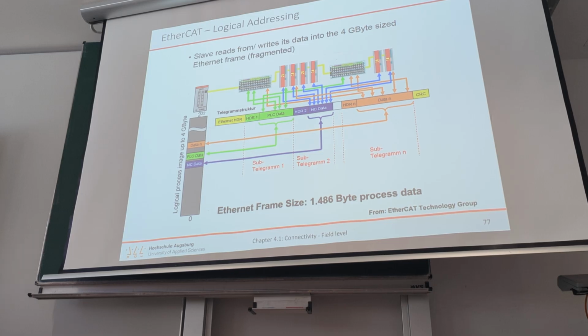If you calculate that, then you see that roughly a frame takes about 120 microseconds, and that's why it was difficult to get control loops that were faster than 120 microseconds. And that's when they don't use the standard Ethernet technology anymore.